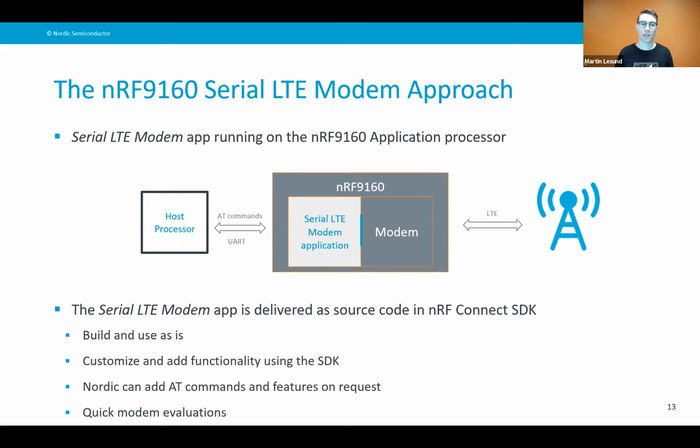It's an application we call Serial LTE Modem. You just run that on the application processor. Then you can use a host processor to send AT commands via the UART, for example, or SPI, depending. Default it's UART. You can build it and use it as is, send AT commands, set up an MQTT client, connect, etc., just through AT commands.